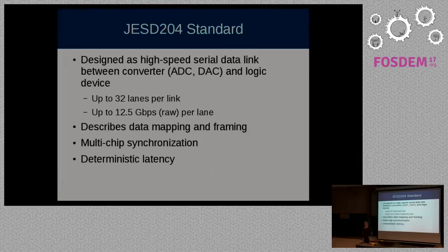Another thing that the JESD204 standard offers is multi-chip synchronization. So if you have multiple chips, multiple ADCs, multiple DACs, and want to capture synchronized data or transmit synchronized data, the standard defines how to do this. So it is no longer chip specific. And the other very important thing is deterministic latency. We will talk about this in more detail in a moment, but it basically allows you to make assumptions about how much time will elapse between when the conversion was done and when the data arrives at your logic processing device.